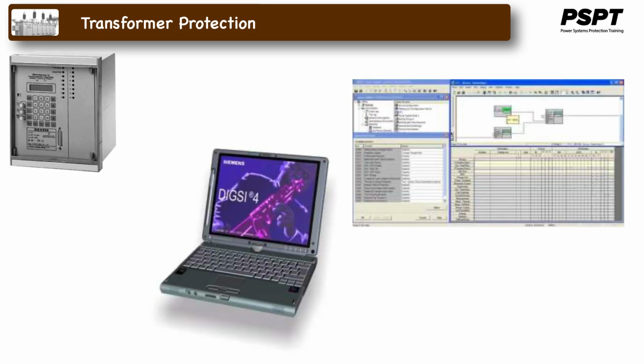The Siemens 7UT513 can be accessed using the DIGSI operating program on a compatible PC, using the handy front connection or the substation control interface that can be a fiber optic interface or other standard substation control system interface. Alternatively, this can be an isolated interface using RS-232C communication standard.